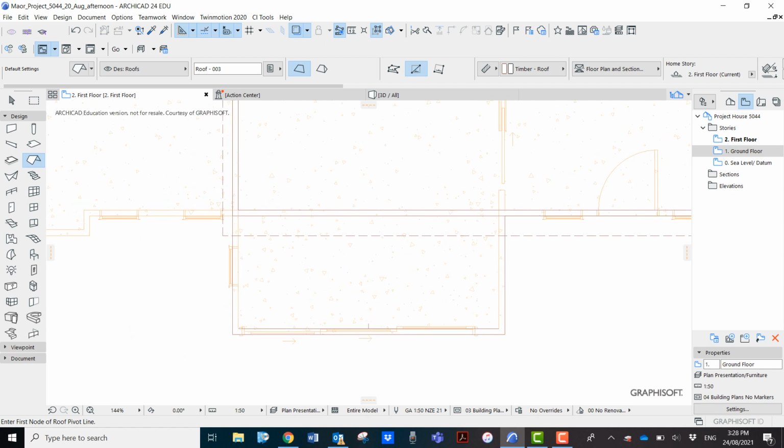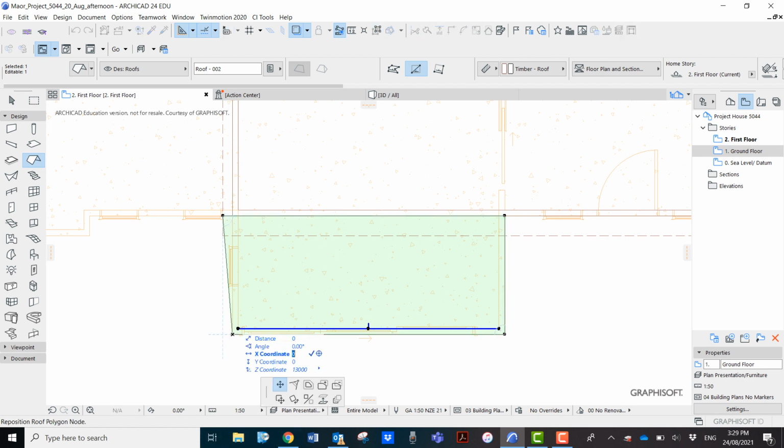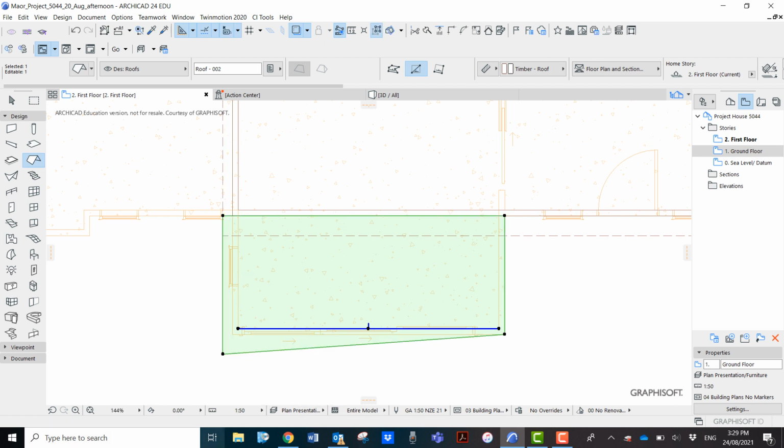Okay. Now, again, you might want to be in the roof tool, select that, and then say this has to go out x 150 minus. Do the same down here, x 150 minus, but we'll say y 300 minus as well, which is a fairly big eave actually. We can change that later if we like, but I'll just do all these things now and we'll see how we get on. Now, if you've already done barges and eaves at a different size, don't worry about it. It's okay.